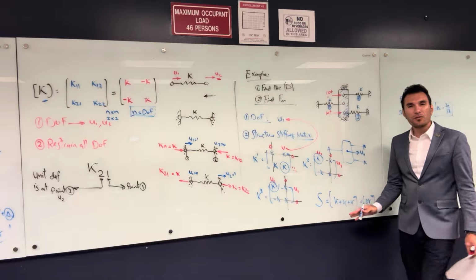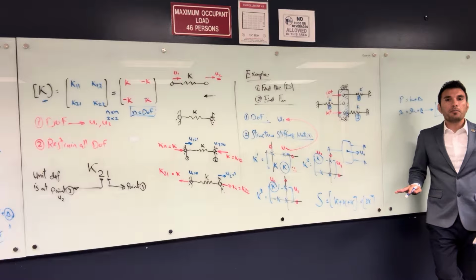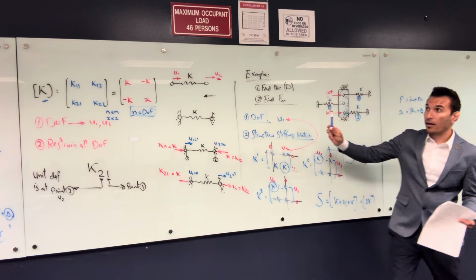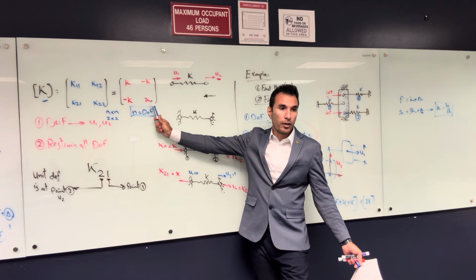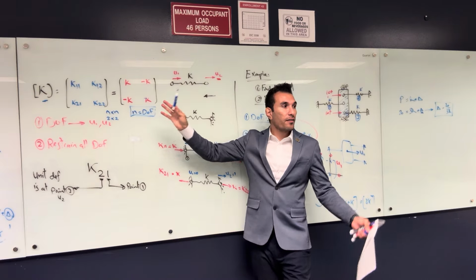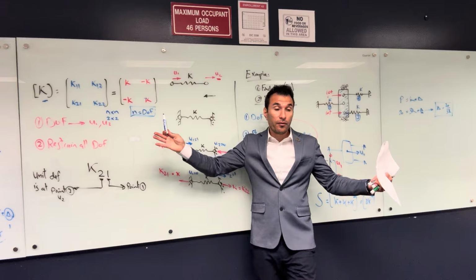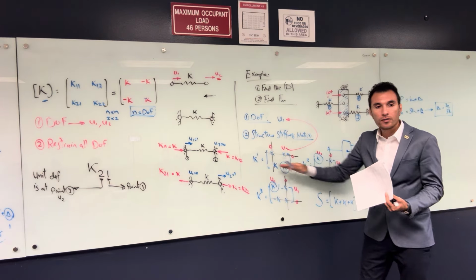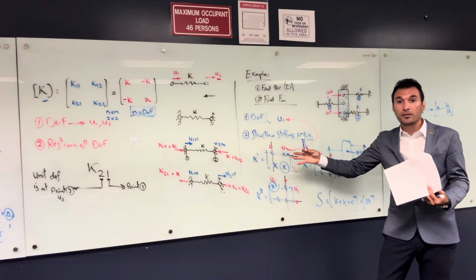Okay? Does anybody have any question? So, the concept is a little bit hard, a little bit confusing, but this is how we build the structural stiffness matrix. Look at that. You cannot solve a structure like this with all degrees of freedom at all ends. We build it free, and then when we know that these degrees of freedom are fixed or cannot move within the structure, we zero all the columns and the rows that come from this fixed degree of freedom.